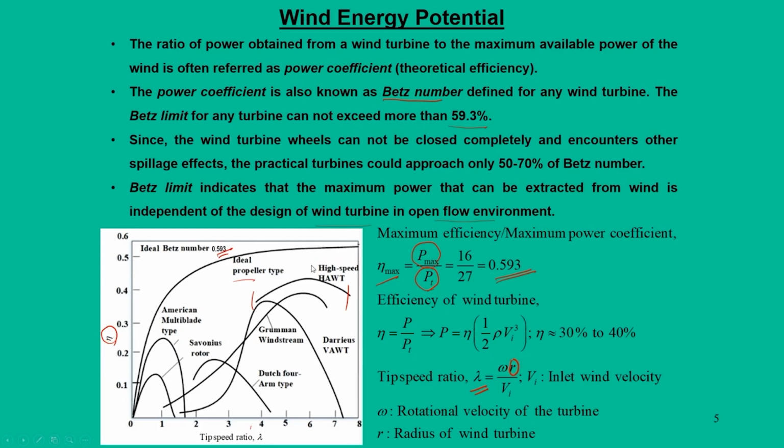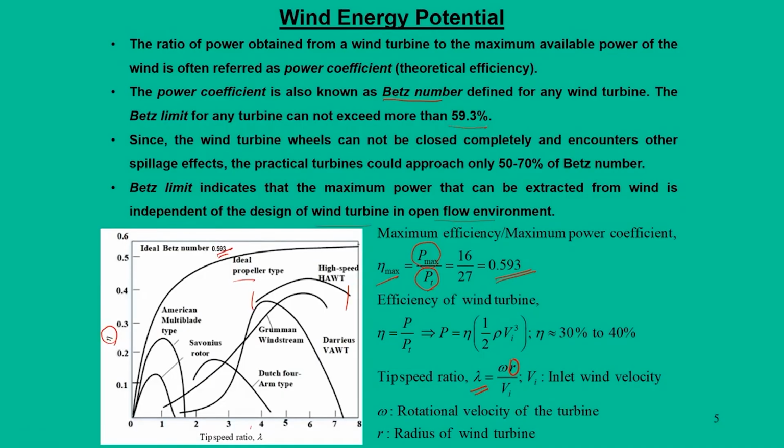In other words, wind has the potential to work up to the Betz number, but in a given wind turbine at a particular geographical location, it is not possible to reach that number. So, we have different ways to design the blades of the wind turbine to achieve this.